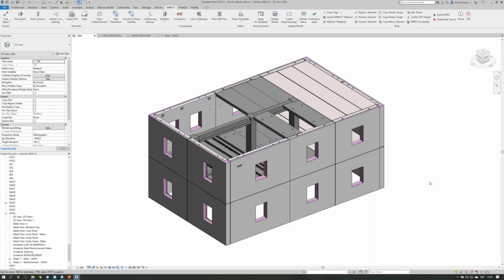But if you want to use a specific reinforcement, like for a cantilever, then you can use the Revit Rebar tools, just as you know them. So it's possible to add additional reinforcement. You can also use add-ins for reinforcement if that's what you're using currently.